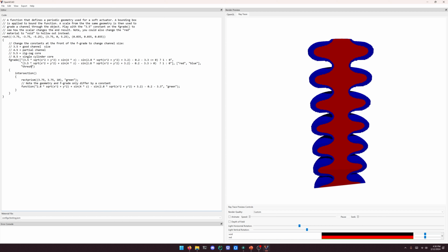So one of the things to notice here is the threshold mode. So I'm using the threshold mode here to create a hard material transition between these two boundaries without defining any separate geometry. So I'm not using any kind of unioning or Boolean operations. This is purely a material definition in a single region of geometry, right? Allowing us to define both a red and blue material.